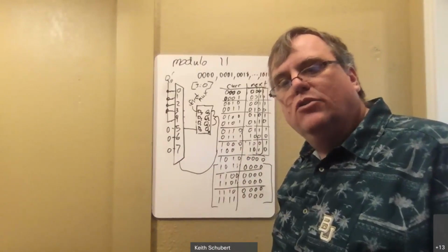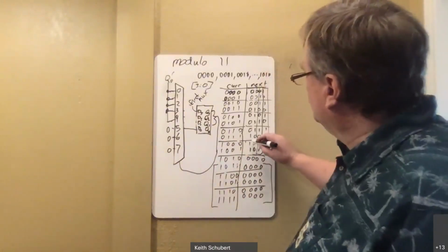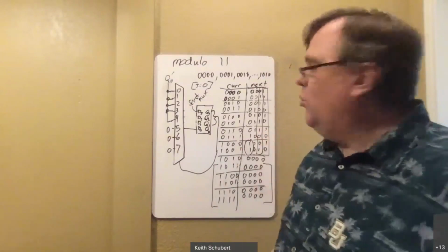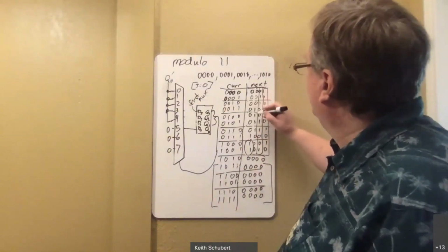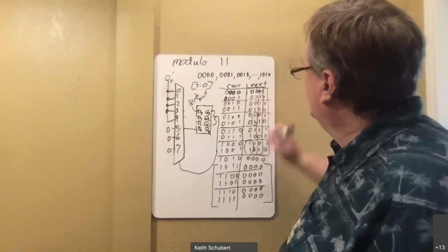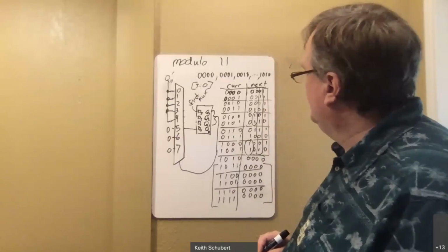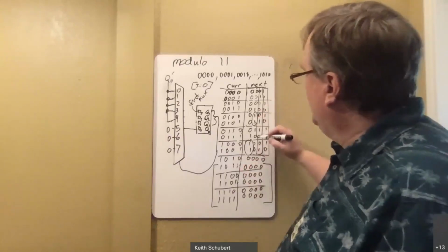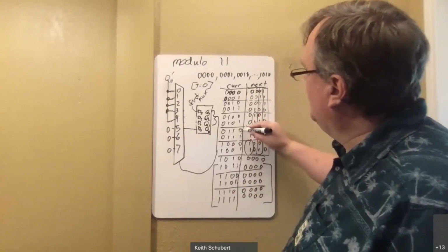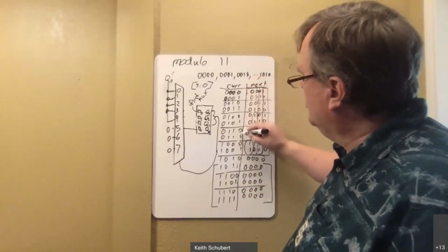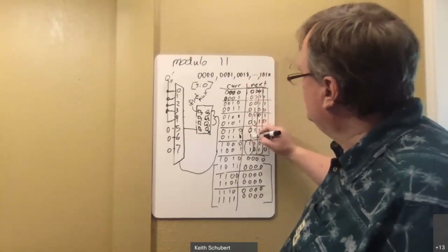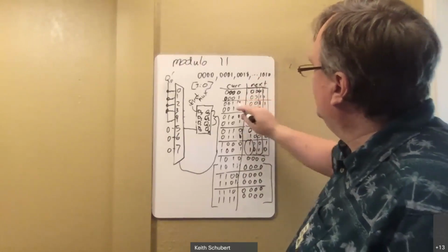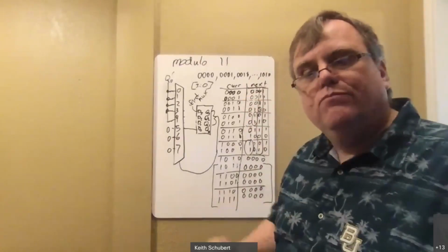When do you get a 1 instead of Q0 or Q0 prime? When both of the numbers are 1s. So if you look right here, I've got 2 1s. They're both 1s, so in that one, I put a 1 there. Here in this column, I had 2 1s together, so I put a 1 as an input for that one as well. If they're both 1s, I put a 1. If they're both 0, I put a 0. If the pattern is 0, 1, which is the same as the least significant bit of my current, Q0, then I put Q0. If it's the opposite, like 1, 0, I get Q0 prime. Good?